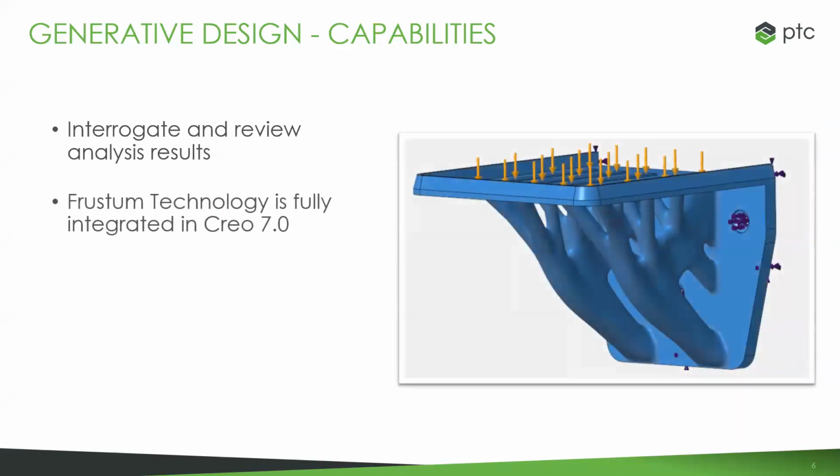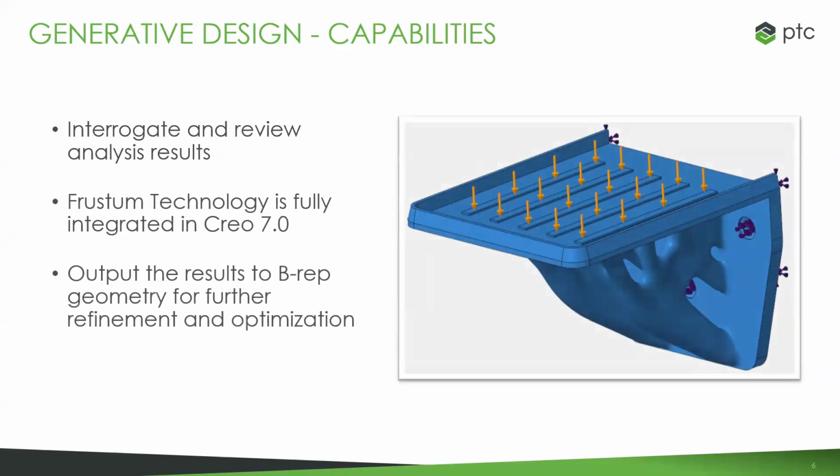And part of the reason that we're able to do that is because it's all integrated right from within Creo. So we took what we have in this generative tool, built it right into the modeling environment. It's not a separate window or different software we have to switch over into. You just go through and build out the design. And once the system generates the design, you've had the chance to go through and review it, you can go ahead and output the results into a full solid.